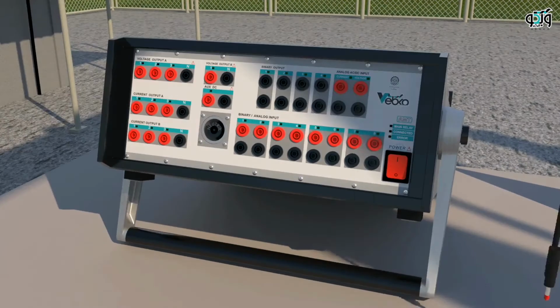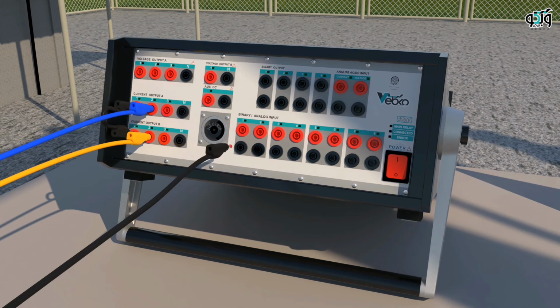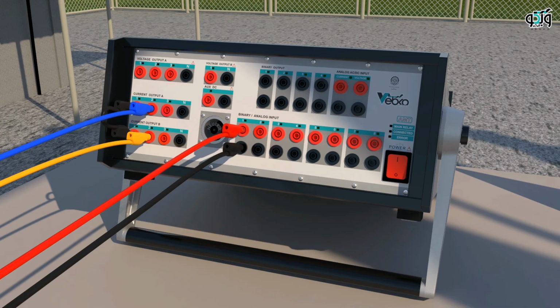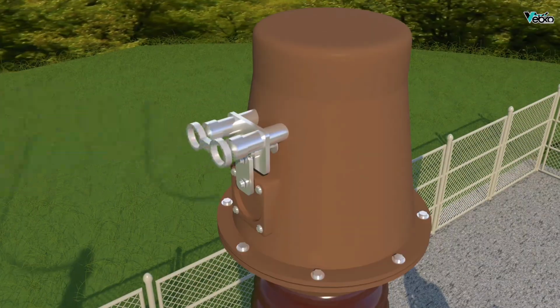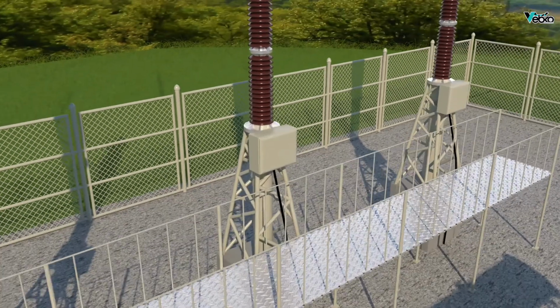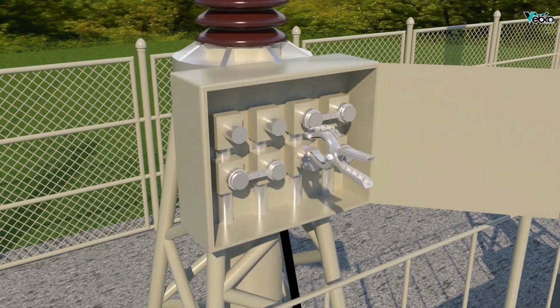In this picture, first phase of current groups A and B are made series so that the maximum burden of the device is used. Then, the outputs of the device are connected to the CVT. To measure the caused voltage difference, input number 1 must be used. It should be noted that in this wiring, the voltage connectors are connected ahead of the connectors of current injection.